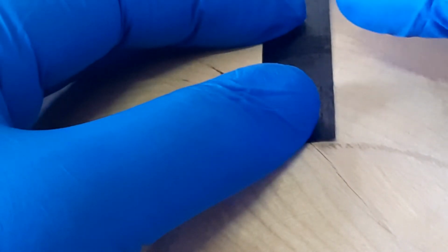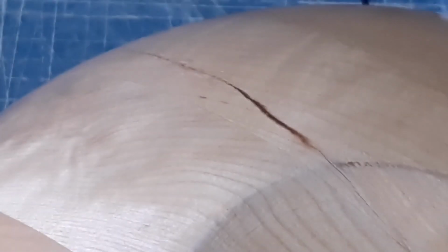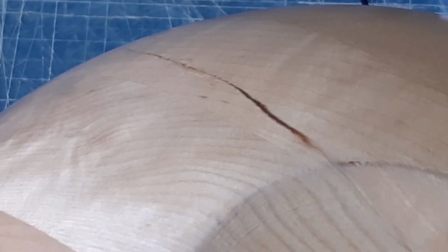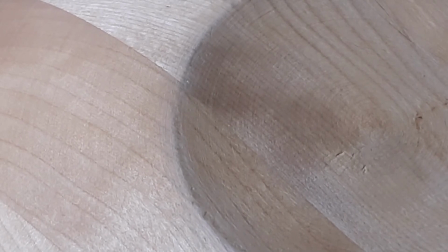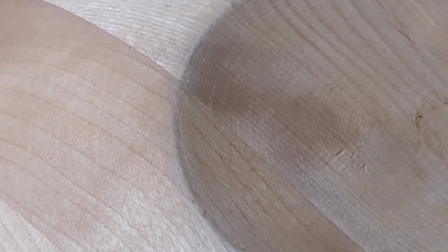And suppose you lay it up and vacuum bag it, you would see that this edge would crimp and this edge would be flat, and that is not what you want. You want the entire surface to be flat. So that is why that kind of material is a menace to put on, and we avoid that.